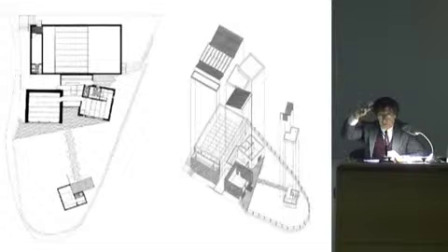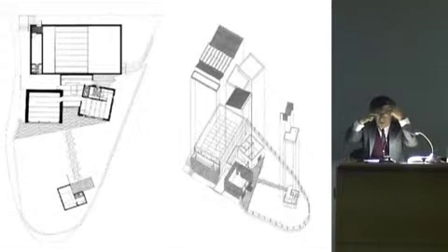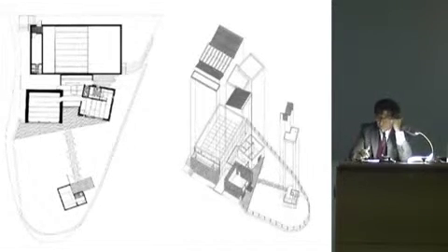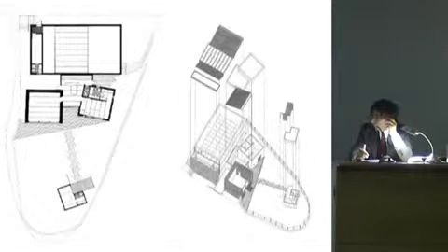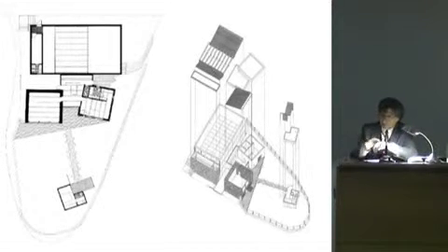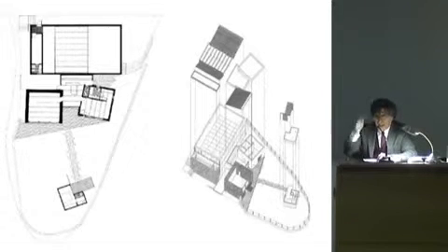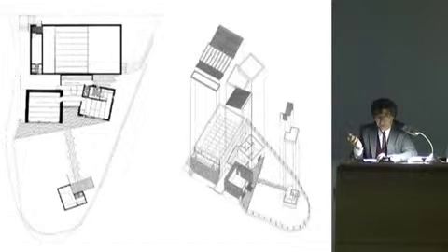And when you reverse this situation, like you do on the roof, you can work on a reverse gable roof. You know it because it's in any construction manual you've studied. You can do the same with the wall. So the load-bearing wall goes inside. In the chamber you find the isolation, and then you have the facing, the building skin facing.